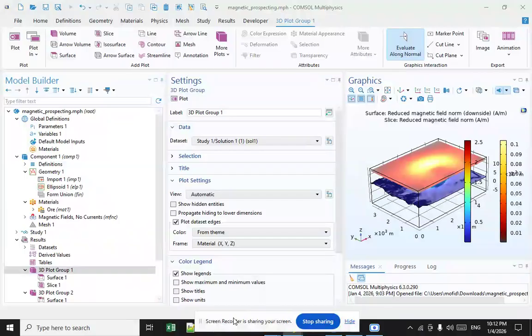Mining of banded iron formations involves coarse crushing and screening, followed by rough crushing and fine grinding to comminute the ore to the point where the crystallized magnetite and quartz are fine enough that quartz is left behind when the resultant powder is passed under a magnetic separator.